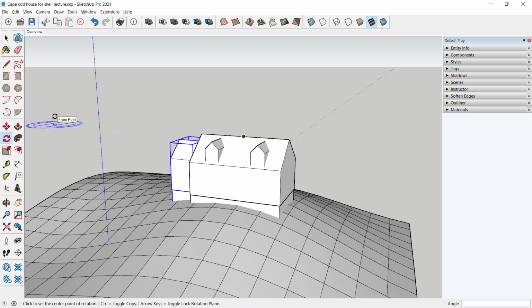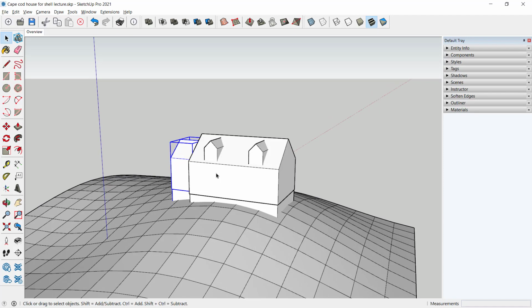Now, there is a disadvantage to that, which is sooner or later you actually need to make a floor plan which shows the interior of the model. And unless you live in a virtual world, walls have thicknesses, floors have thicknesses, even foundations have thicknesses. So we need to use those special tools that SketchUp has to give us some wall thickness, but there's a little bit of strategy involved as well.